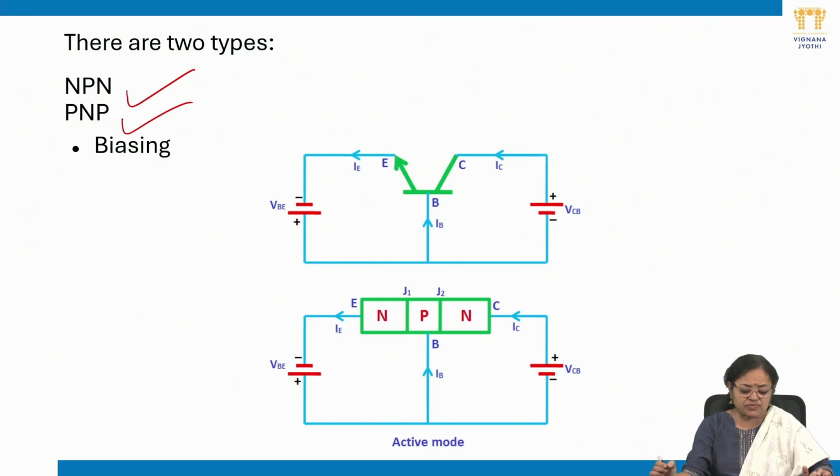For example, the first figure shows us an NPN transistor. The arrow indicates the type of the transistor. The arrow tells the direction of the conventional current and the type of the transistor. In NPN, the arrow is "not pointing in", so we can remember the arrow in that way. Here the emitter terminal, base terminal and collector terminal are shown.